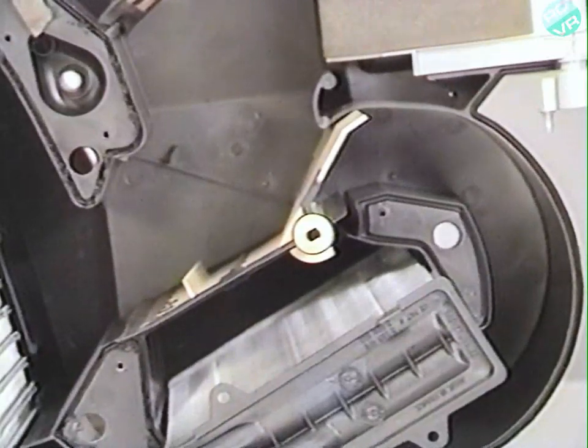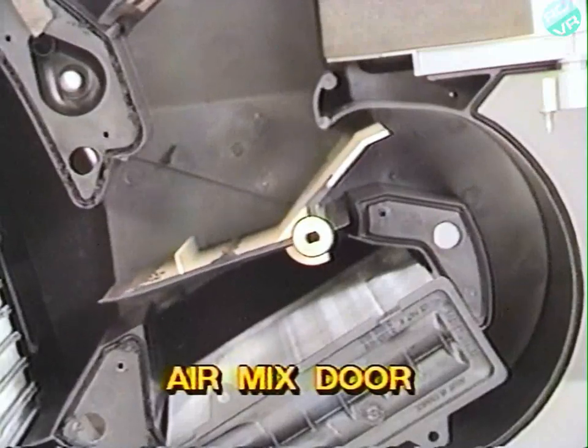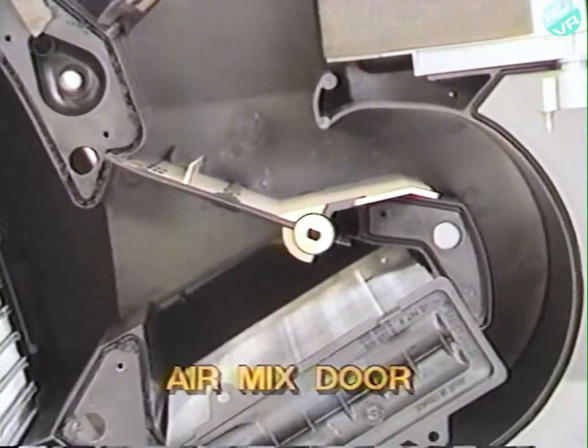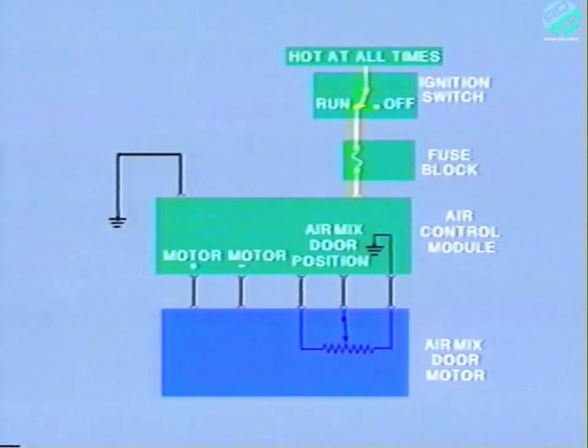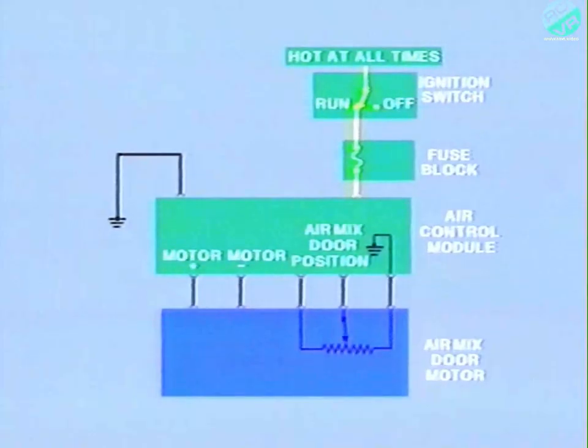Another output of the ACM is the air mix door in the plenum. This door controls the amount of air passing through the heater core. It's operated by a 12-volt motor which receives current from the ACM. To sense air mix door position, the ACM uses a feedback system. The module sends a 5-volt signal to the air mix door position sensor.